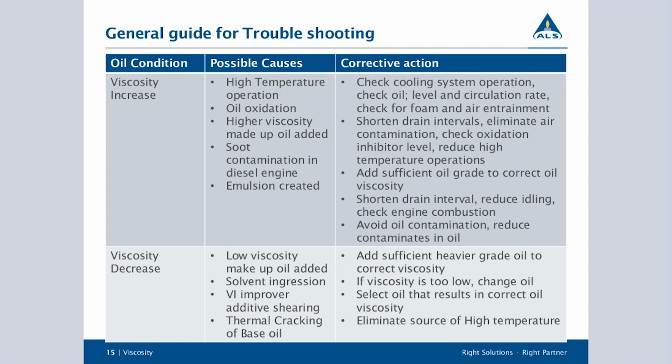The reason shortened drain intervals is in there twice is sometimes you are trying to get the most useful life out of your oil, but if you're seeing that every time you change your oil, it's not in good condition, it might be something that you consider based on your own maintenance program, or even based on your oil analysis, that your drain interval does need to be changed. And sometimes if your oil is operating really well, you can extend that drain interval, but you do have to check with the OEM, with your product data sheets, as well as maybe shooting a quick message over to us to ensure that it's right. You also just want to avoid any type of contamination and try to reduce contaminants in your oil.